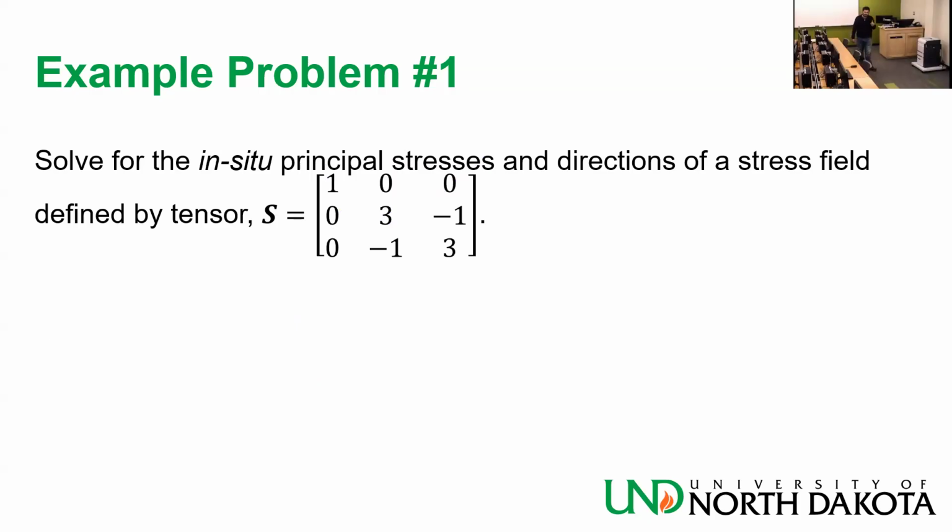If it's not diagonally symmetric, it means that I have an unstable stress state, something that won't be stable in the long run. It might be the case that right now I have some sort of motion, some sort of rotation, something is moving, and I have this very temporary stress state. But in general, if you get a non-diagonally symmetric matrix, it means that something is going on. Pinch yourself. Either somebody is playing a prank on you, or you made a mistake somewhere.